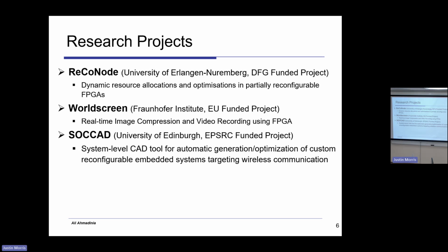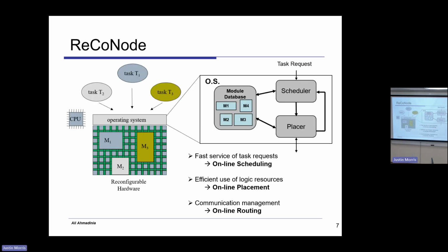Could you put the next slide? So what I did, we designed an operating system within the FPGA that could manage the scheduling of tasks, placement, where we place them, and how we're going to route between these modules online and on the fly when we partially reconfigure the device. Could you do the next slide?